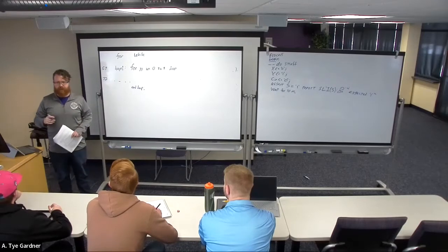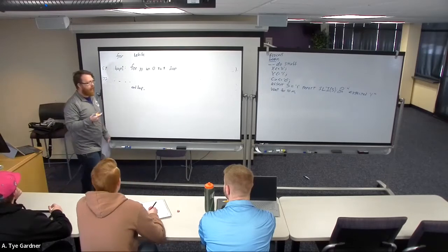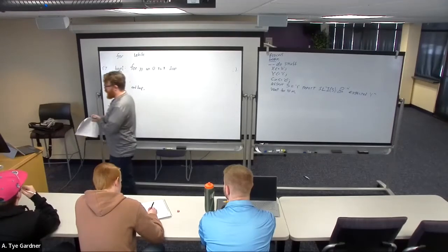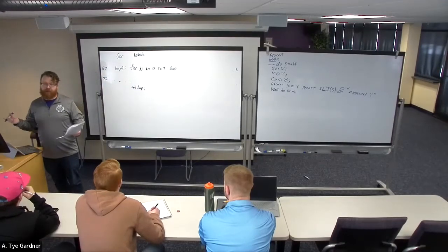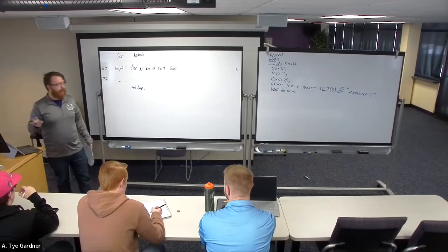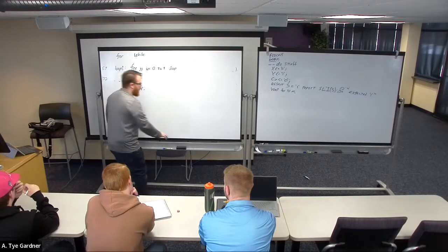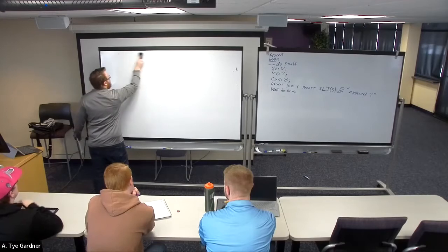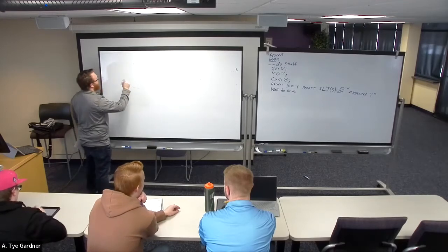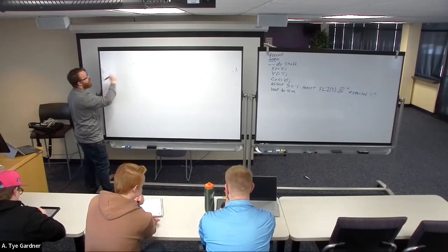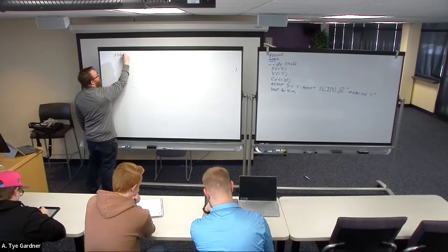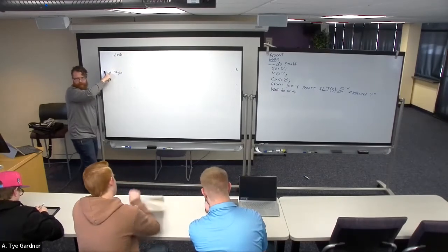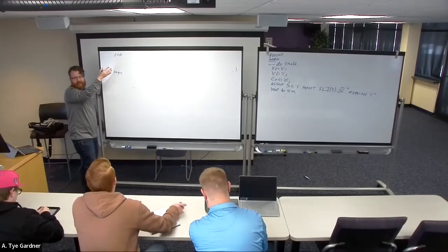I mentioned constants before in the lab, but I think it's worth mentioning again since a lot of you haven't used it. Constants are another useful test bench item, and they're used all over the place. We're going to use them in the project upcoming. We declare them in the same location that we would declare signals. Say we're in a design source somewhere. After the architecture, before its begin, is where we declare things.